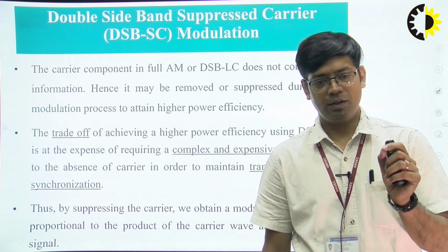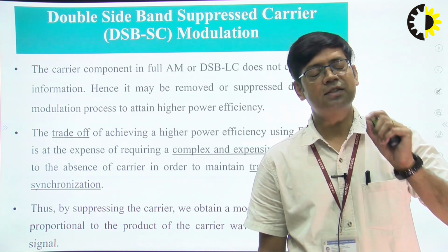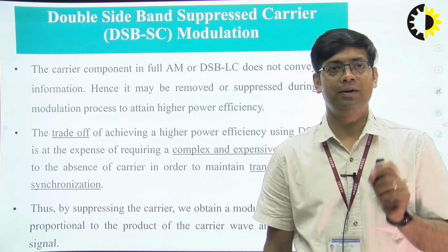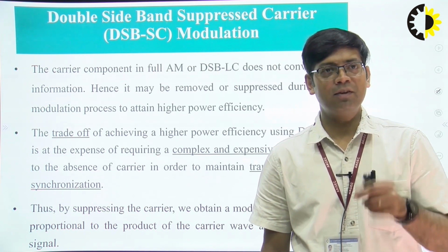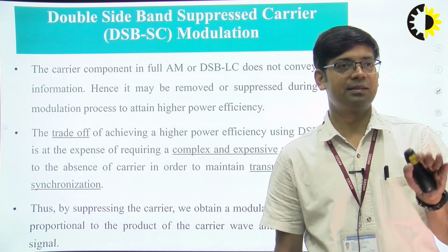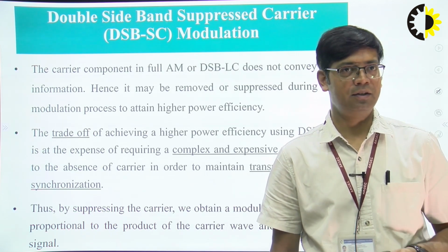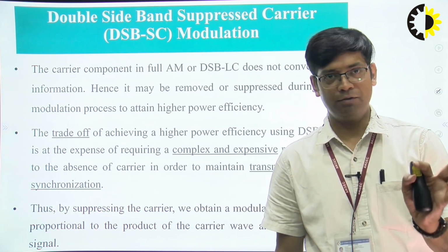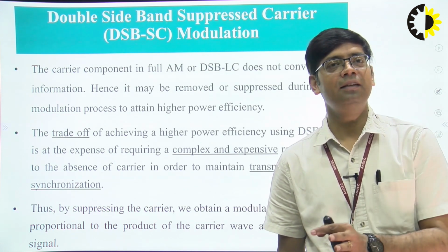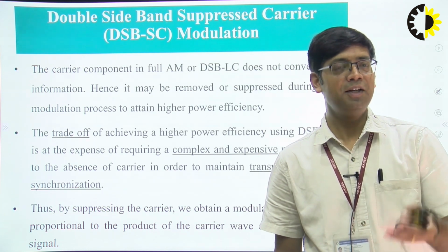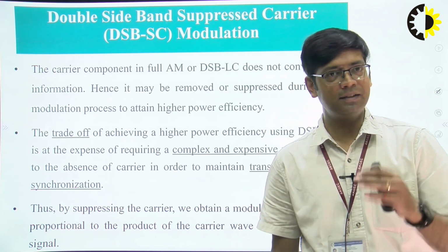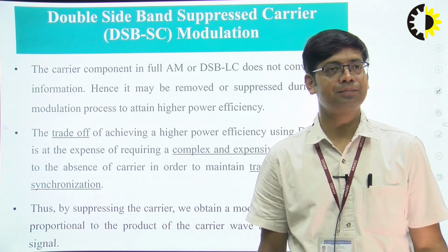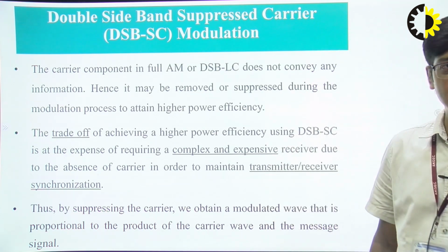and if in this transmitted signal we have to save the power, then we have an option to suppress this carrier signal to a great extent. We can only transmit the sidebands which carry the information, and at the receiver end we can demodulate the sidebands into the original modulating signal format. So, today we are going to discuss it.